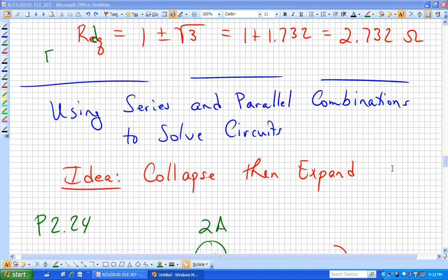But in this case, I sub B was 2 and V sub 3 was 7, both positive, so there are 14 watts being supplied to the rest of the circuit because the current is coming out of the positive terminal. It's not going in. It's not being absorbed. It's being supplied. It's supplying power.